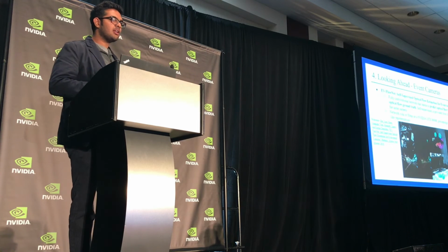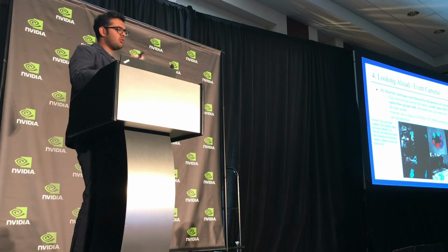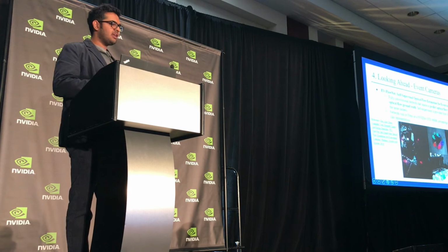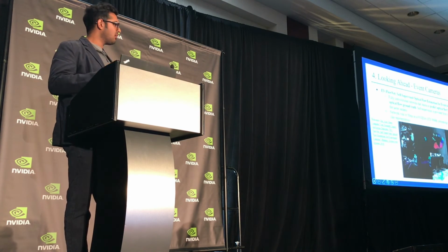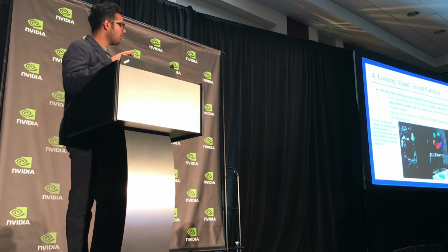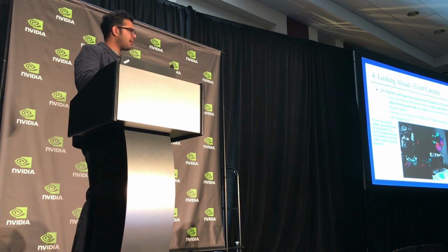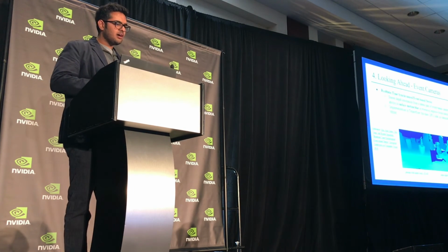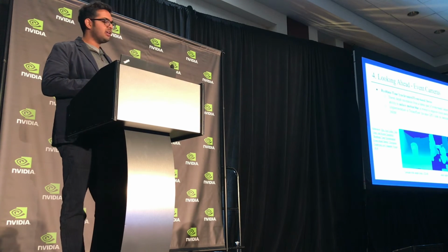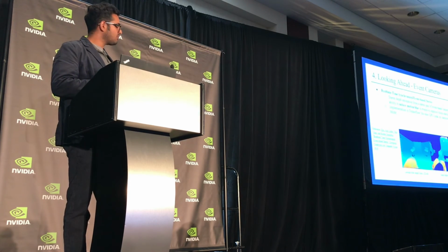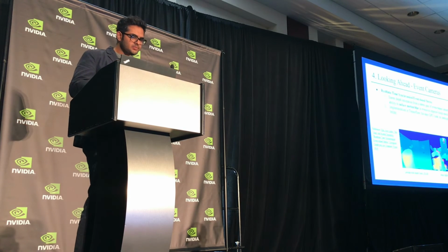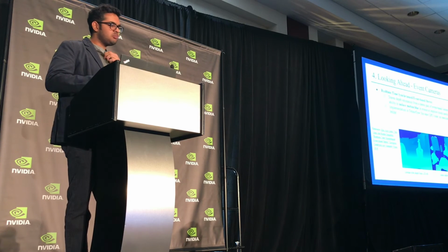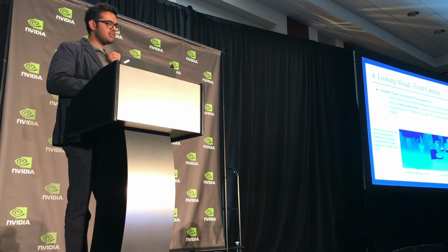So it does really well in dark environments, and this deep learning algorithm runs in around 50 milliseconds on a GTX 960, but we've flown this on our Orbitty carrier TX2 at around 10 to 15 hertz, and we got the same results. This is some work he's also done in event camera-based depth estimation, also running on a 960, which is a laptop-grade GPU, but it also runs at around 10 to 15 hertz on the TX2.